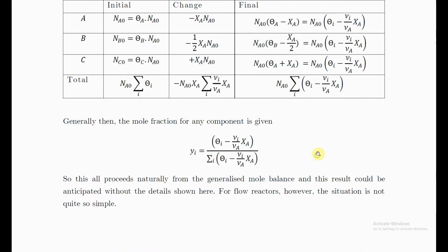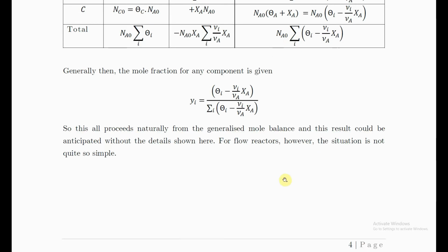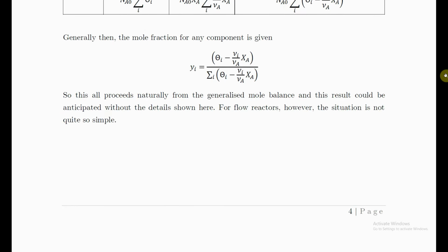And especially given that the batch reactor is not in flow, so fine, the pressure can go up, but the number of moles is what it is, dependent only on the reaction rate. And so I'm not worried about all that, and so I'm just going to go ahead and use this. So you could have just anticipated this result, but we did it sort of for practice right now. Now let's look at a case where it does make a difference.